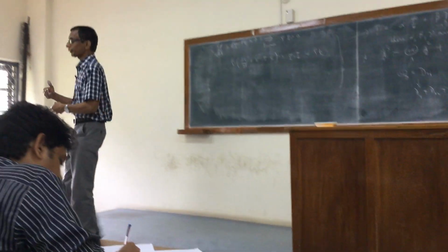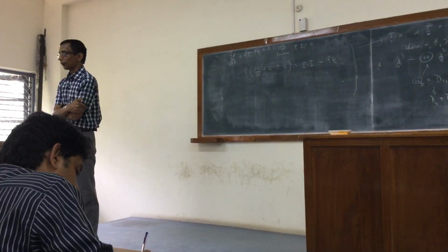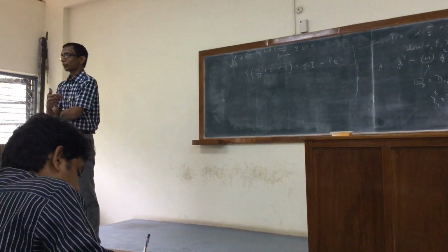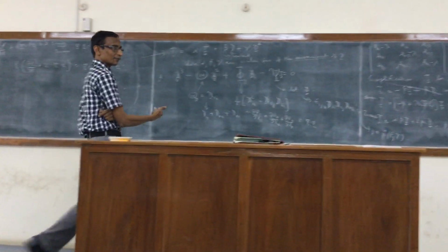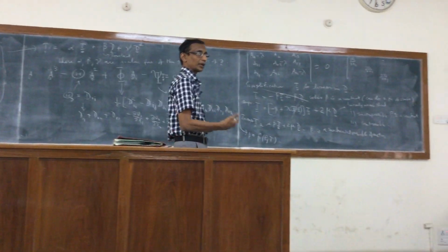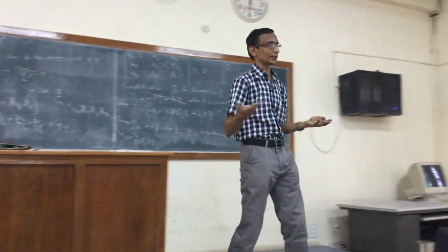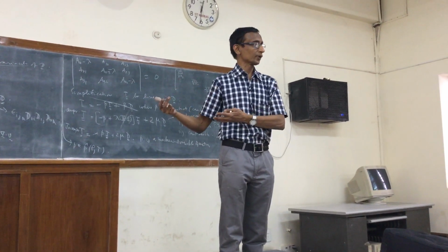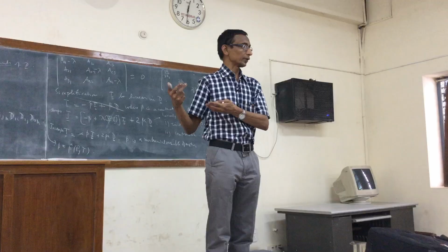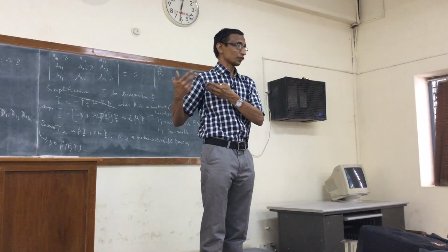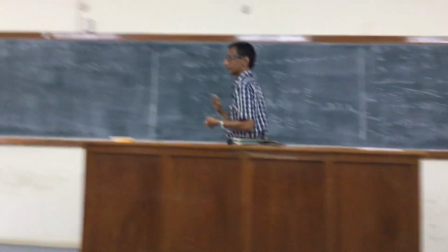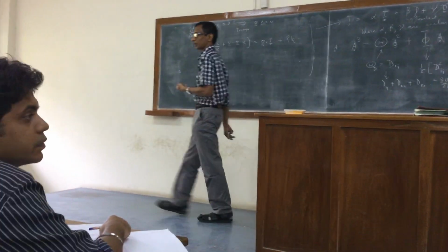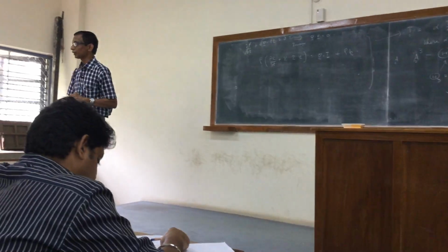So it depends on the density and temperature. Whereas for the incompressible fluid, the density itself is a constant, so the question of the variation of pressure with density doesn't arise. The pressure becomes a variable to be determined by the equation of motion. Of course, you have to solve the equation of continuity together with the equation of motion in many cases to get the pressure. Right? So you'll see the exact meaning of this later.